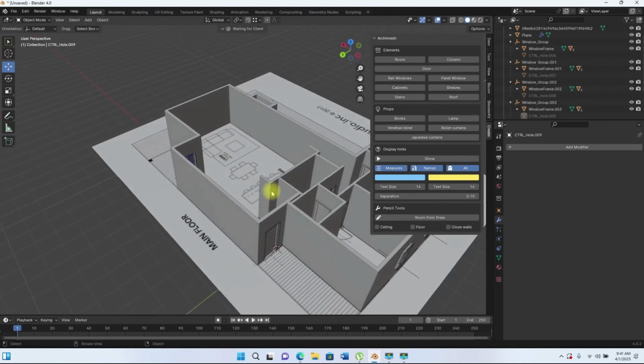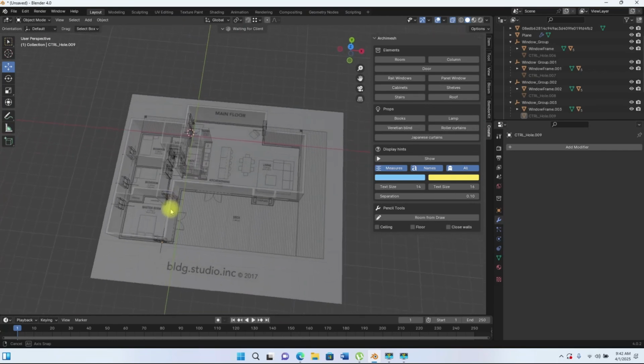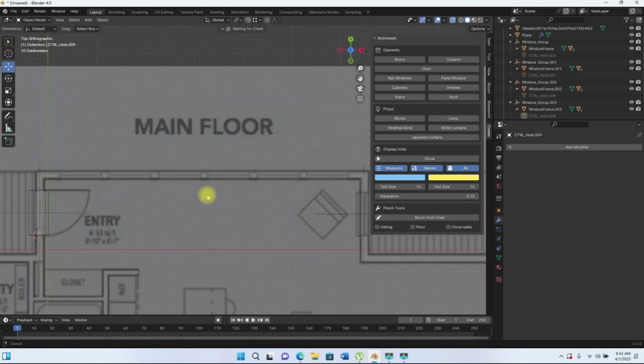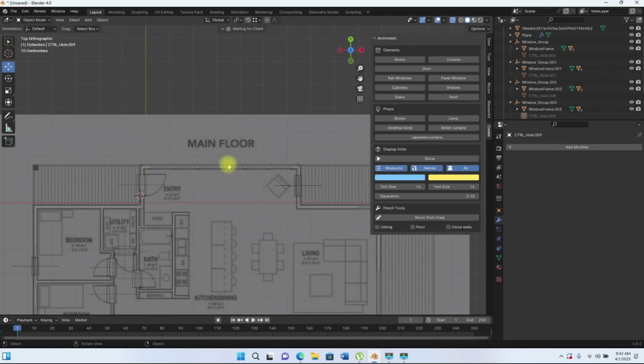So the next thing is this panel. If I take this back to, you notice right here, there is a panel here. So we want to create this panel. We have 1, 2, 3, 4, 5, 6. So this is like a curtain wall, curtain panel that goes more like the normal height of a door, right? So we want to create that curtain panel. So what we will use in creating that is panel windows. They are still considered as windows, but not just the normal ones, these are just panel windows.